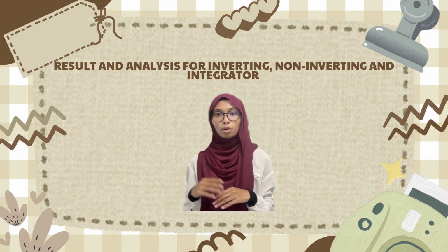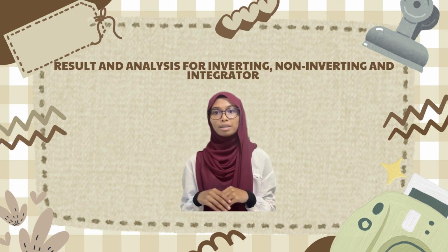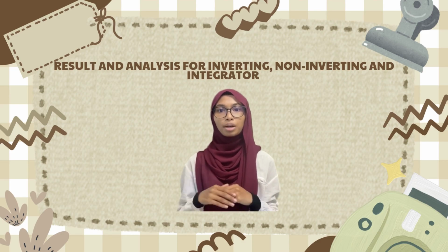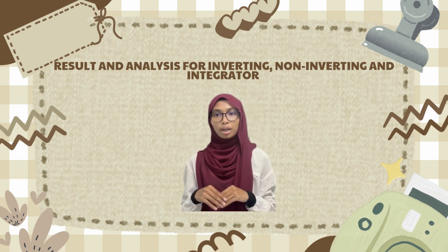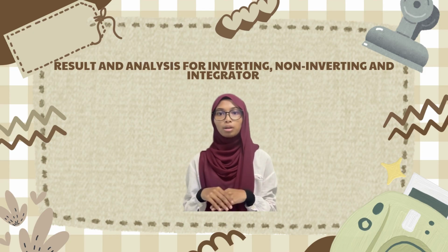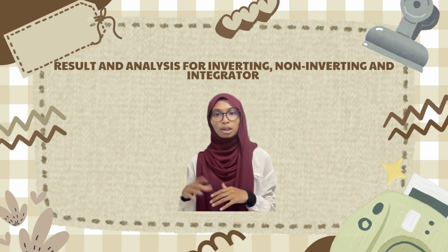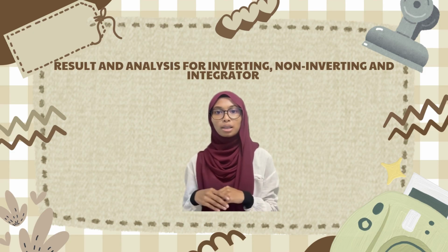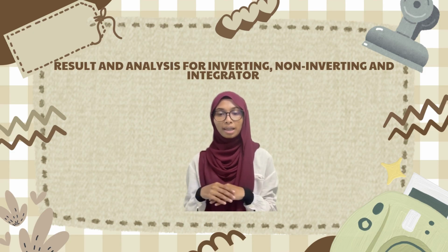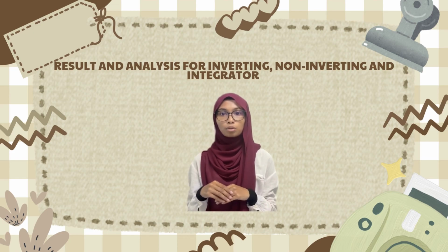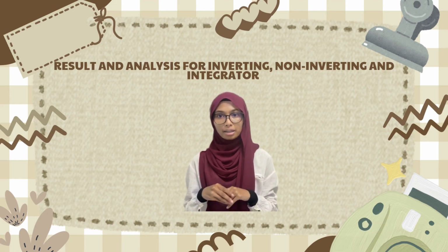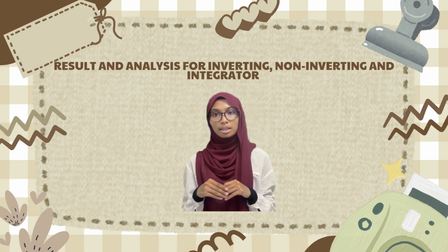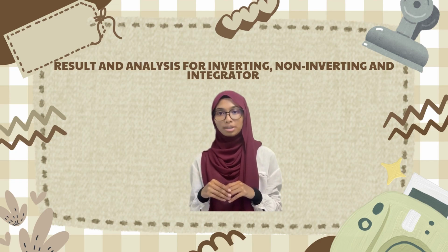Vout for the integrator op-amp is negative 1 volt after calculation, while the experimental value for Vout is 2.86 volt. The 10 mega ohm resistor is placed in parallel with the capacitor specifically to address the instability, which provides a DC path for the tiny currents and limits the DC gain to a manageable level. There is a trade-off between DC stability and ideal integration when the resistor is added, to guarantee the circuit is practically stable and operational throughout.